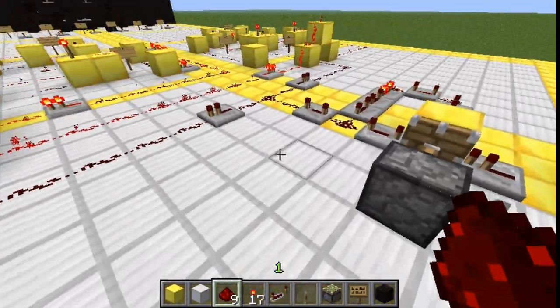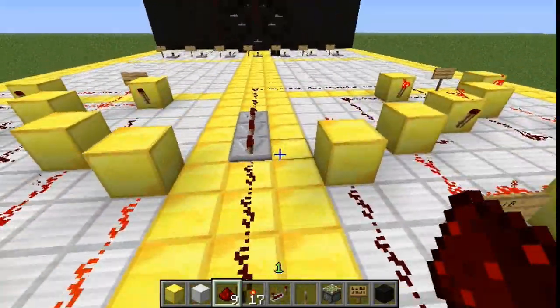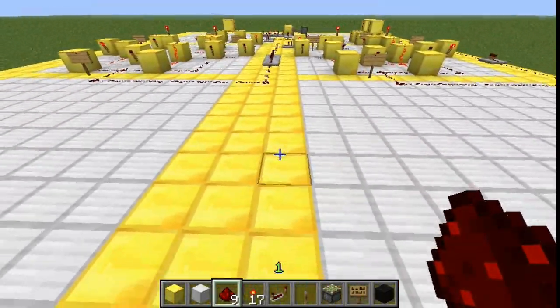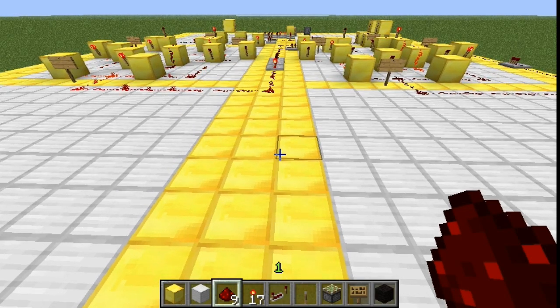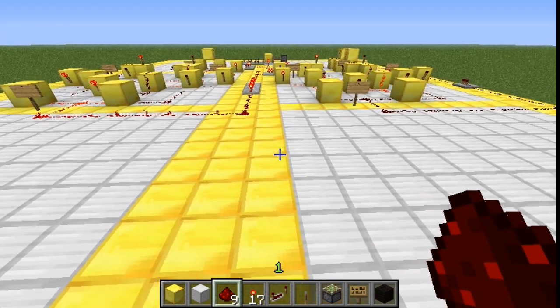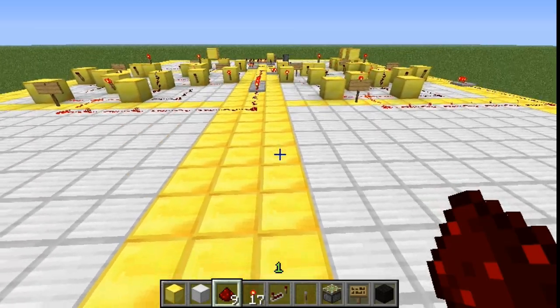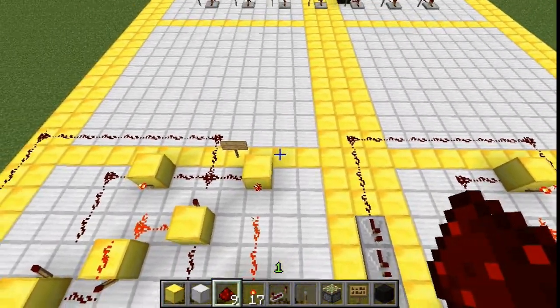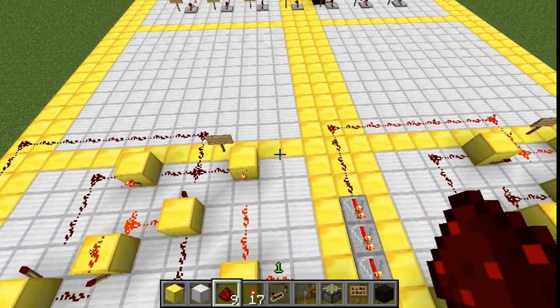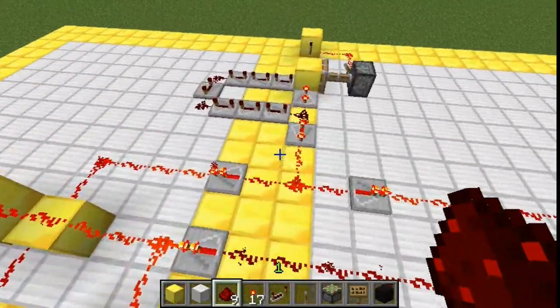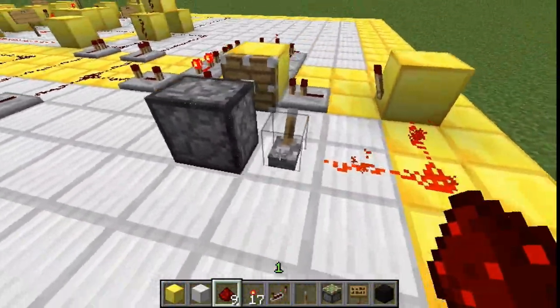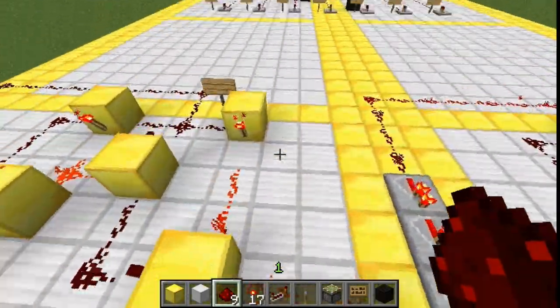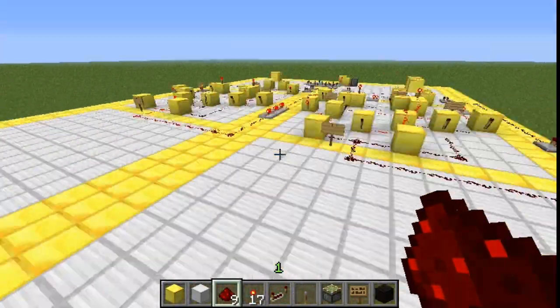So we turn on the pulse generator. Now that we've got the pulse going, we should see the outputs changing. So 0, 0, 0, 1, 1, 1, 1, 0. So just a note, 0, 0, so that's A, 0, 1, 1, 1, and 1, 0. So we've got the correct outputs coming out of there, and there's actually a very nice delay in between, so there's actually long enough time to note what the outputs are.